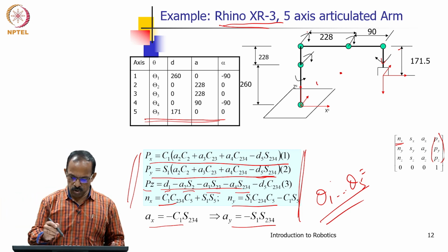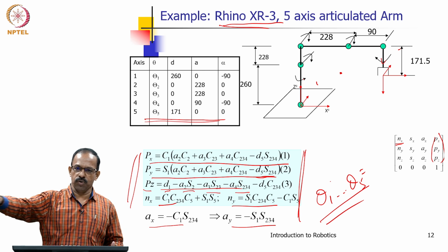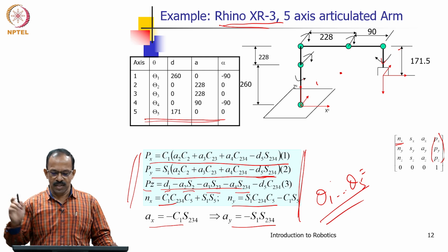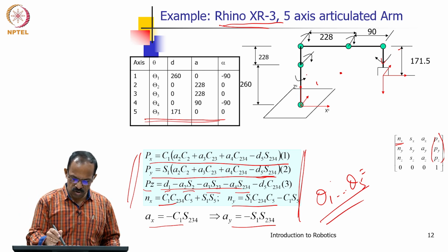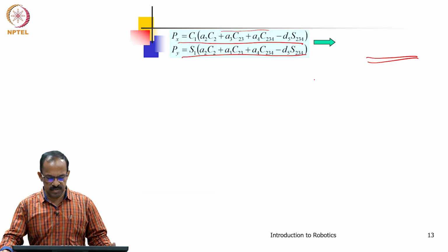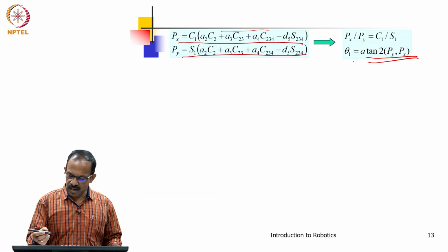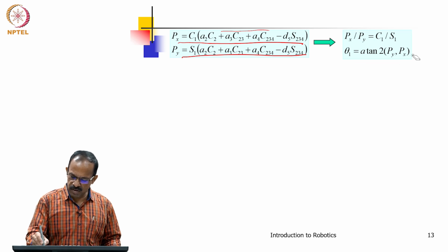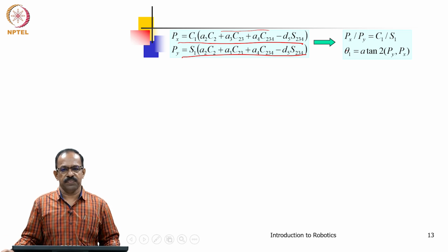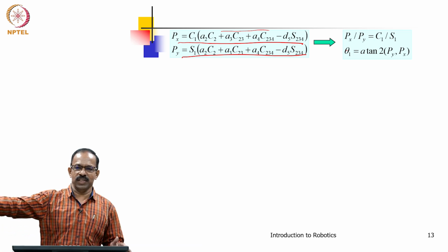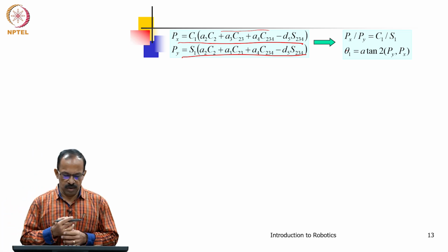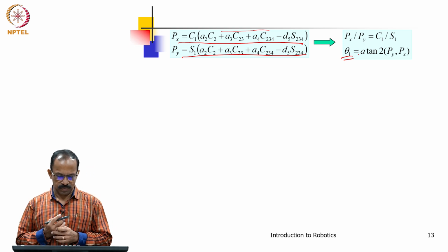That is, by moving this theta 1, it will be coming out of the plane and it can actually reach a y position. So, whatever y position is given, that is decided completely by this joint angle theta 1, and that is very clear from this relationship also. Theta 1 depends on what Py and Px values you want to reach. So, you can come out of the plane using theta 1 only. So, we have got theta 1 now.